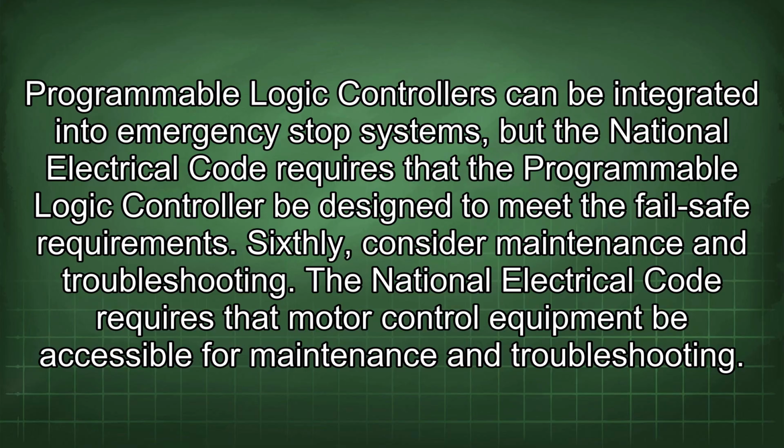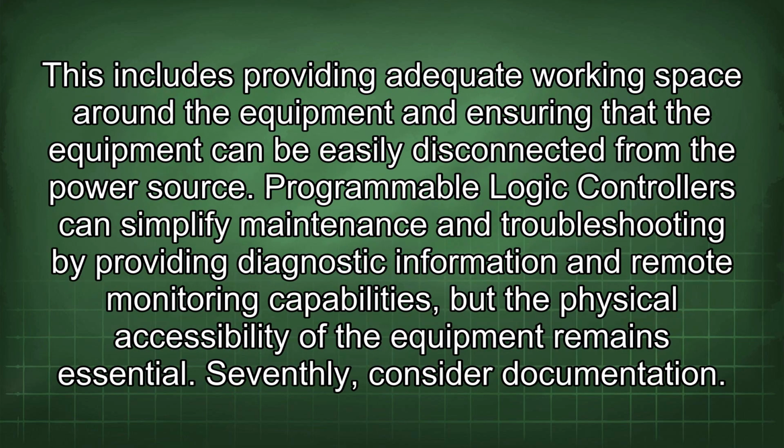Sixthly, consider maintenance and troubleshooting. The National Electrical Code requires that motor control equipment be accessible for maintenance and troubleshooting. This includes providing adequate working space around the equipment and ensuring that the equipment can be easily disconnected from the power source. Programmable logic controllers can simplify maintenance and troubleshooting by providing diagnostic information and remote monitoring capabilities, but the physical accessibility of the equipment remains essential.